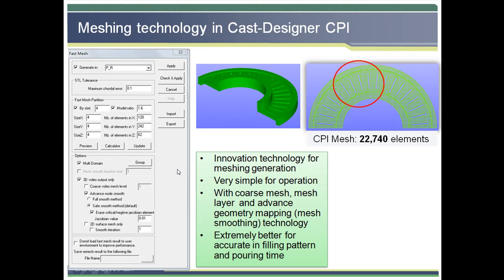We pay a little more attention to the meshing process, since it is always a critical issue and argument between FEM technology and FDM or FVM technology. Cast-Designer is using FEM technology. It is more advanced compared with the traditional FDM or FVM method, because of the good geometry description, better formulation, full coupled simulation, and flexible memory management. All of the above are very important for casting.